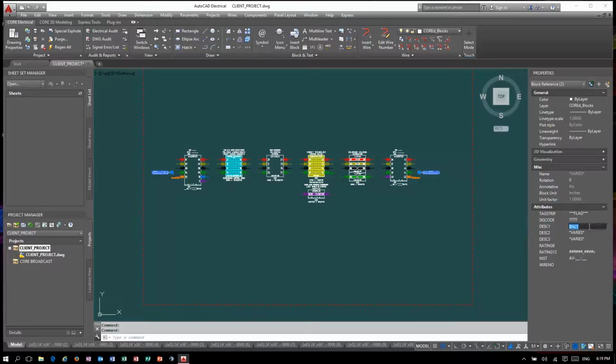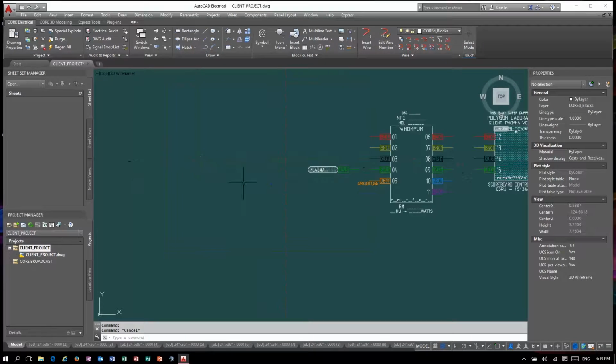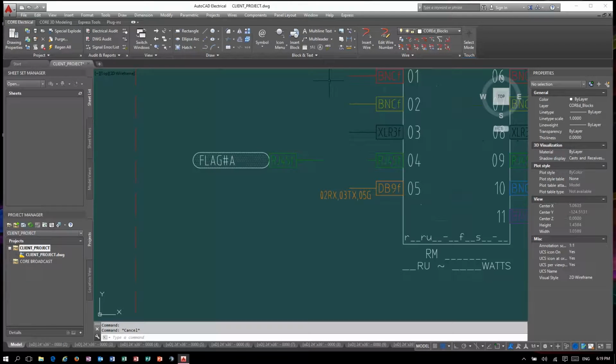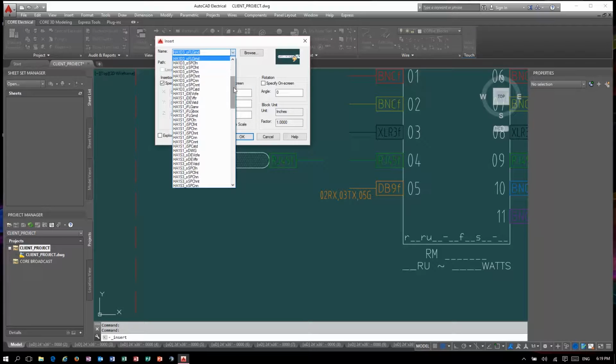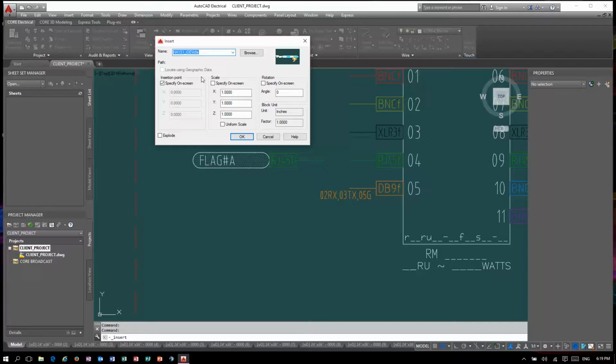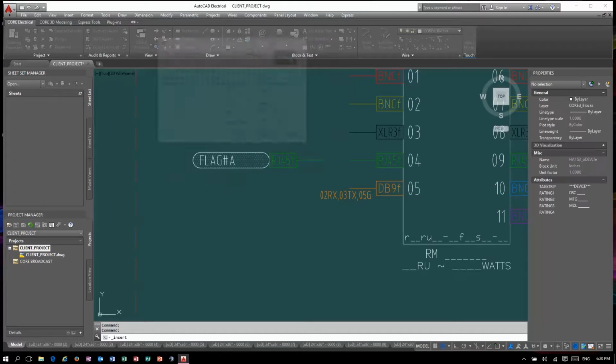Many times, it is necessary to use placeholders for remote or known locations for electrical signals, but the specifics about these devices are unknown during the design. An example of this would be a demarc location for a Telecom OC3 circuit. We know this device is required for the system, and we may even know its location. This remote style device contains two angle brackets on each side. It contains all of the attributes and fields of a dynamic equipment block.